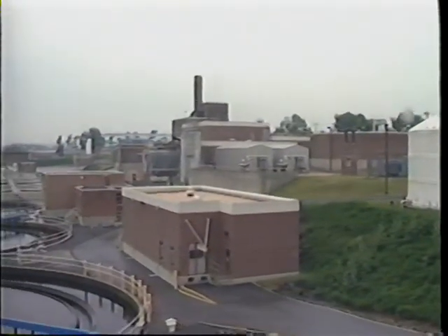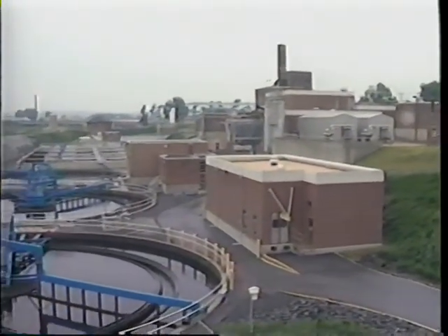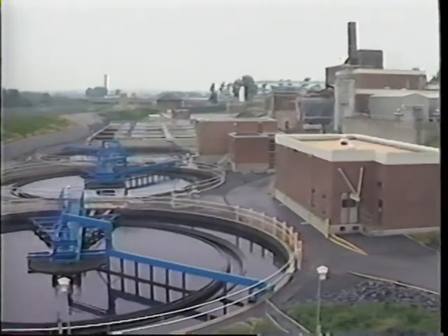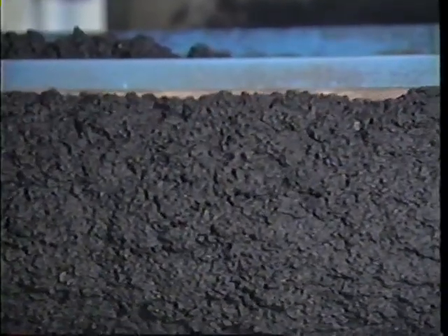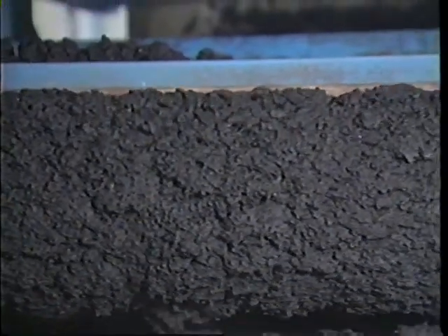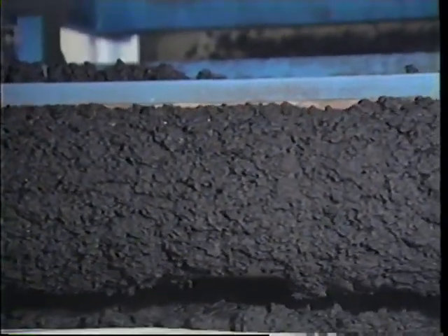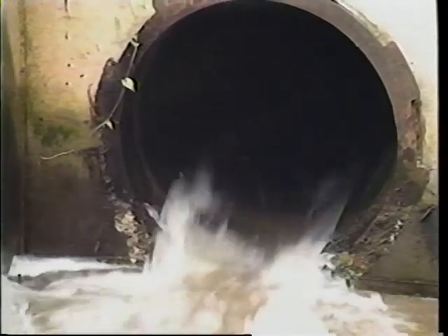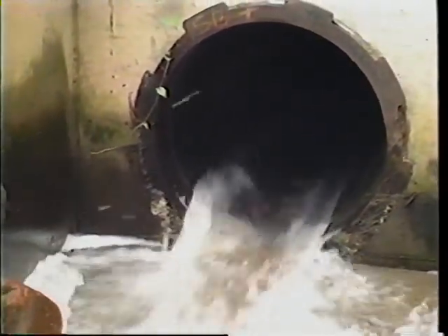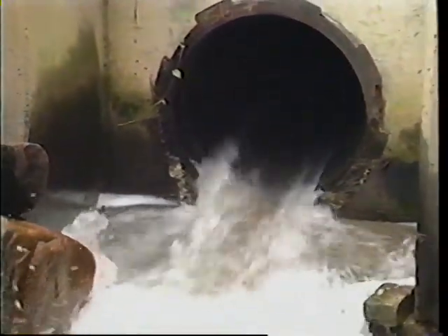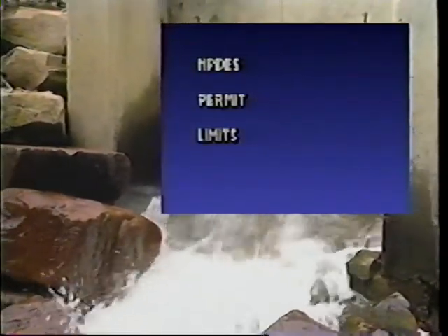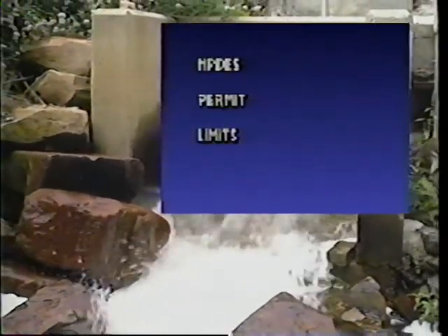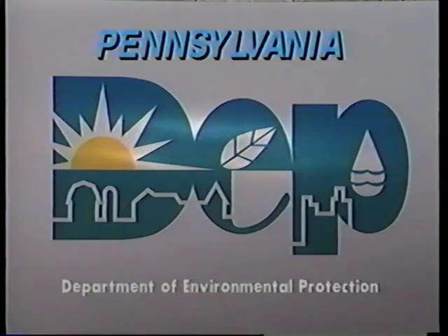It is here, at the treatment plant, that the wastewater will be treated and returned to the water environment of the receiving waters. And the biosolids removed during the treatment process are treated in solids handling facilities at the treatment plant. The degree of treatment and the number of treatment processes used will usually be determined by the discharge limits as specified in the facility NPDES permit by state and federal authorities.